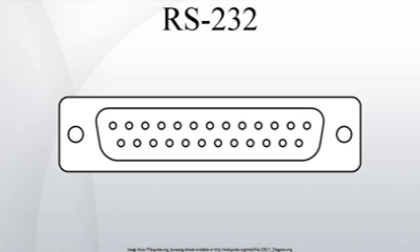RTS-CTS handshaking. In older versions of the specification, RS-232's use of the RTS and CTS lines is asymmetric. The DTE asserts RTS to indicate a desire to transmit to the DCE, and the DCE asserts CTS in response to grant permission. This allows for half-duplex modems that disable their transmitters when not required, and must transmit a synchronization preamble to the receiver when they are re-enabled.